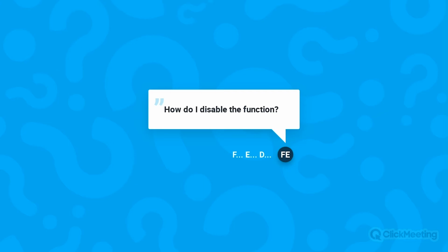We have a question: how do I disable the function? I was going to explain just this when the question arrived, because I forgot to mention it. Basically, to disable this function, we have to switch off the inverter. In other words, we don't set parameter 140 back to 0, because we understand this is a special movement, a rescue operation, or we are moving in maintenance. So in order to disable this function, we have to switch off the inverter and switch it on, and when we switch on back, the control will be the previous one, so synchronous motor in closed loop.